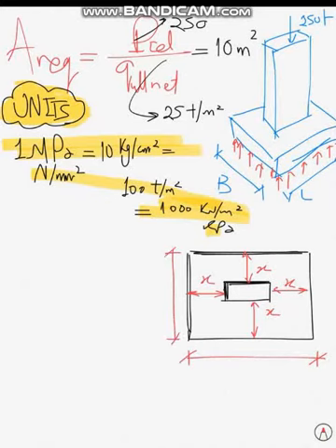So the dimension of the foundation required to determine is, based on the column dimensions, 0.3 plus 2x, and on the other hand 0.8 plus 2x. I assumed a certain extension for the footing x from all sides of the column toward the edges of the foundation underlying the soil.